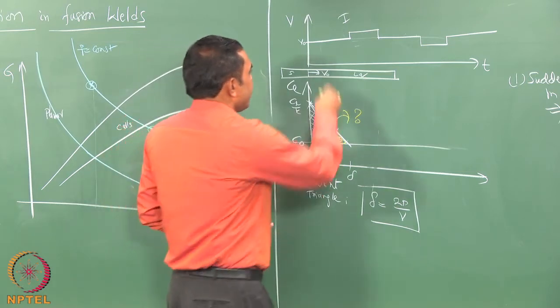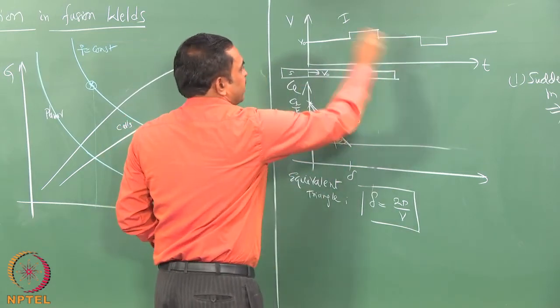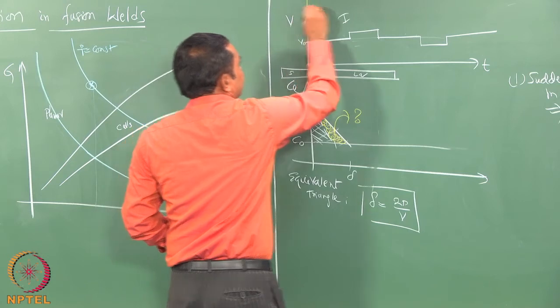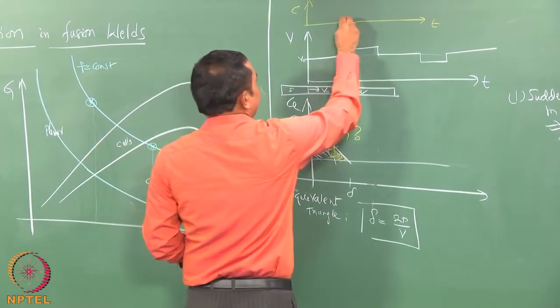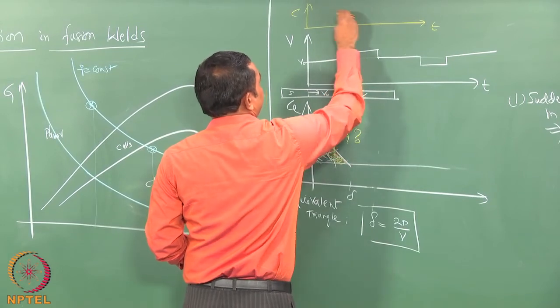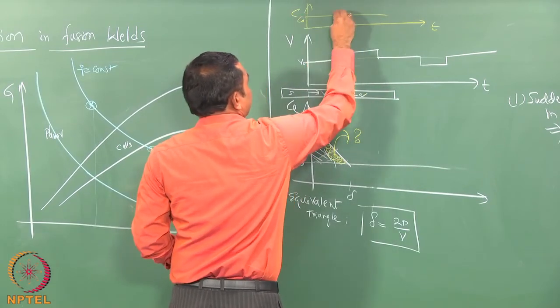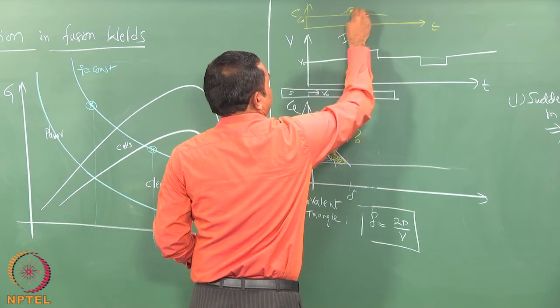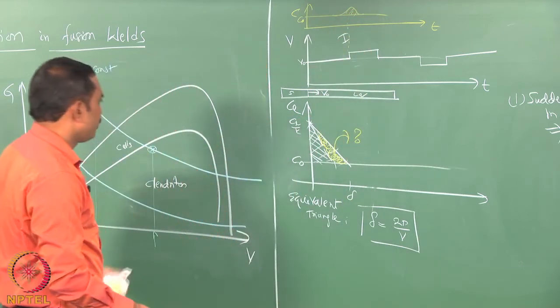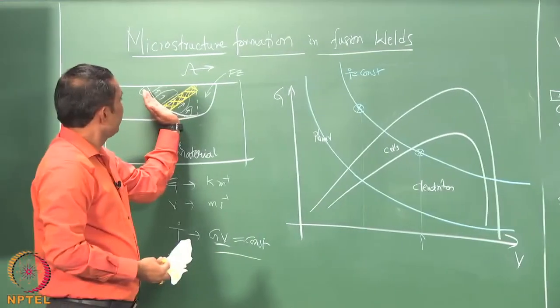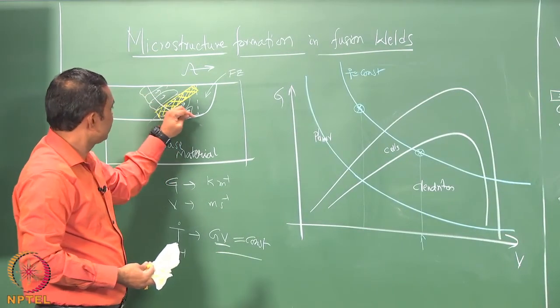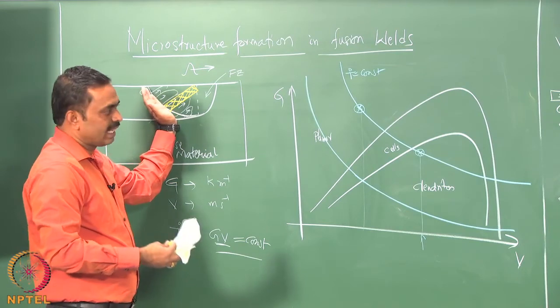So, if you were to plot C as a function of time behind the front, then exactly at this point the solid will have a bump with an excess composition, which means that as this front is moving, there would be an excess solute going along this direction as the velocity suddenly increased.